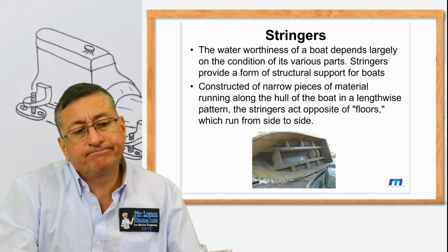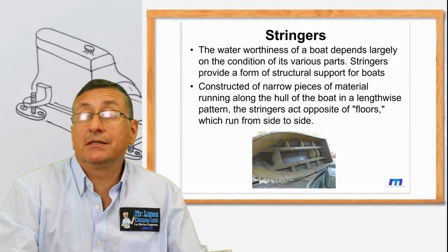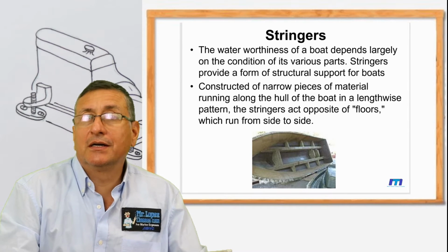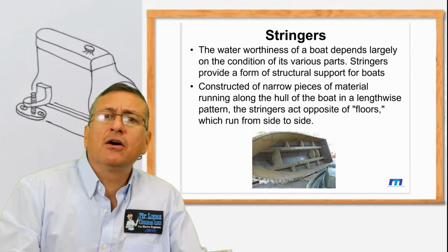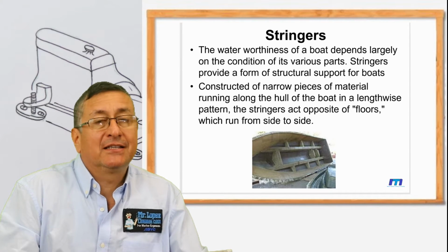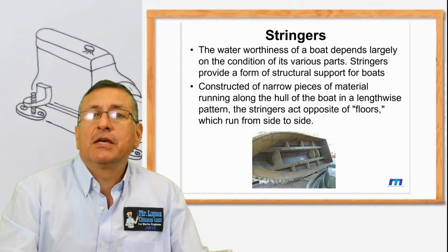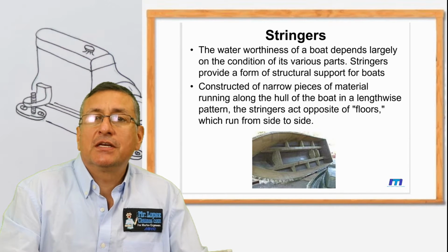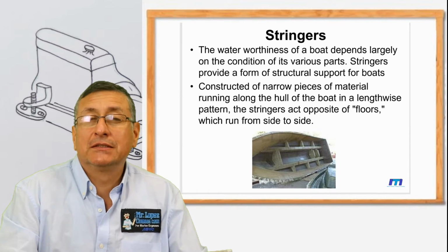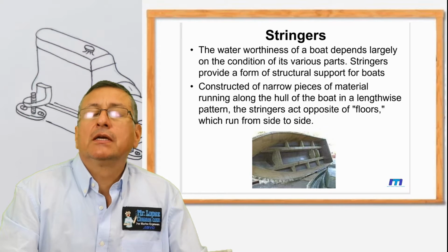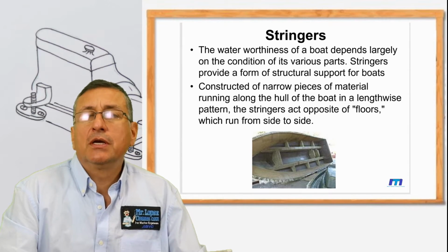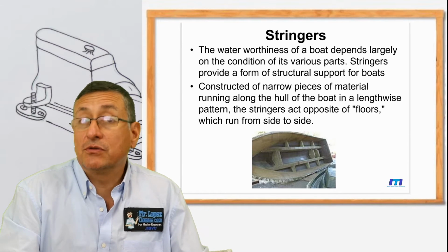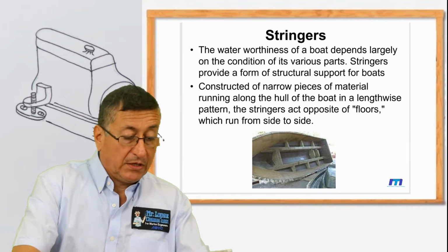Can I repair it? Yes, but it's a lot of work. It's hard. You need a space at home. Also, you need to be careful with the neighbors because you need to cut a lot of fiberglass. That's not good for the environment. For that reason, be careful when you try to buy a boat. Be careful with the condition of the stringers and the condition of the transom.